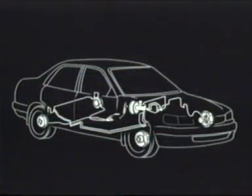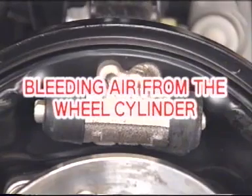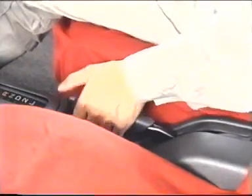Next, bleed air from the hydraulic circuit. Start from the wheel cylinder farthest from the master cylinder. Release the parking brake. Remove the bleeder plug cap from the bleeder plug.